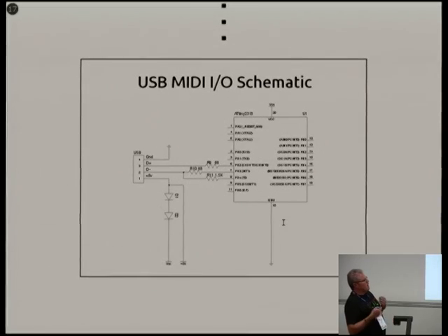USB MIDI. Generally, from a microcontroller version, writing a USB device is pretty complex. You need specialized chips, and there are a lot of timing issues. But at the USB 1 level spec, the system is slow enough that you can write it in software. So there's a company that has written an open source product called vUSB, which is a set of firmware libraries for Atmel chips. In this case, I'm using the ATtiny. Basically, everything becomes software driven.